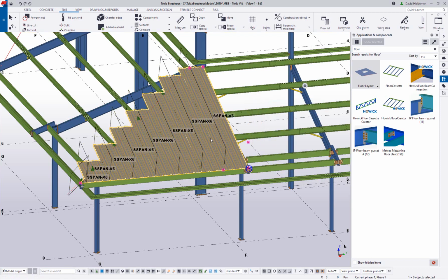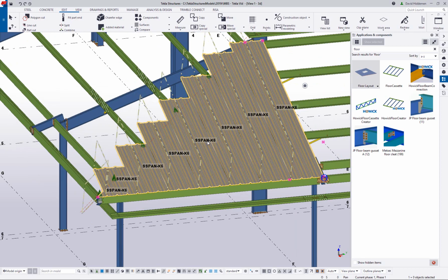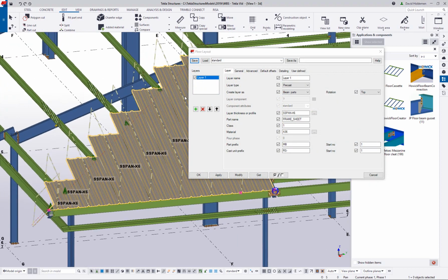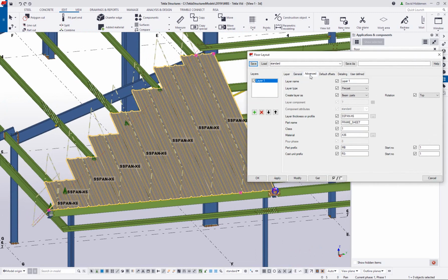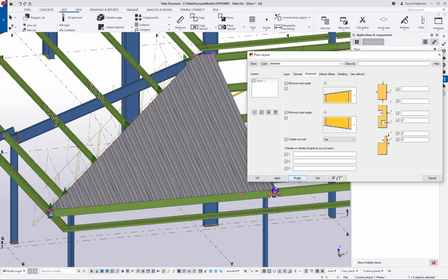Now, as you can see, the settings I'm using right now are again square cutting or giving the rough lengths of these sheets. But this tool does have the option inside, if you go to the Advanced tab, to change this up to give you again more of that field cut or finish cut look. Again, it comes down to what you're trying to represent in the model space. I'm going to go ahead and change that back to square cut just so everything matches, and then I want to show you something else that's neat about this tool.